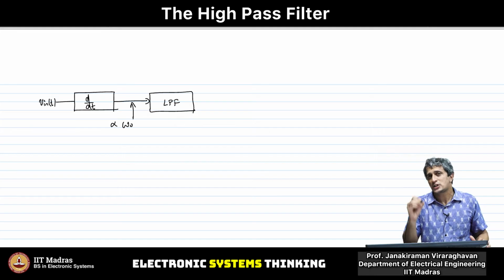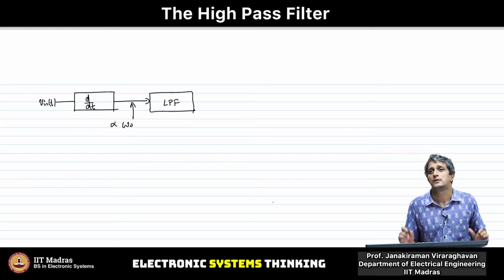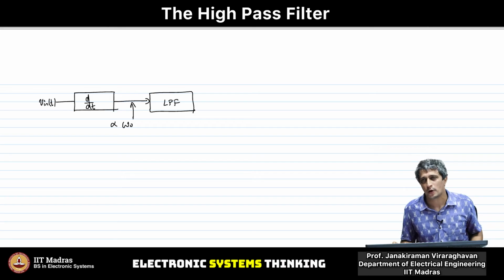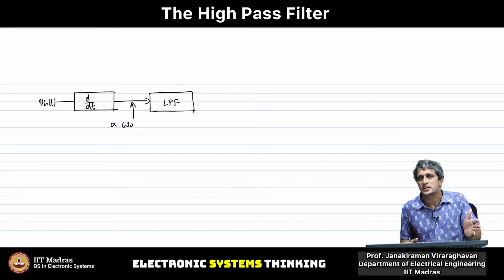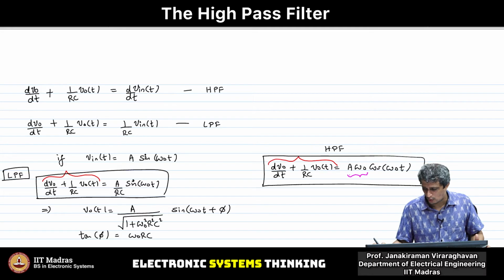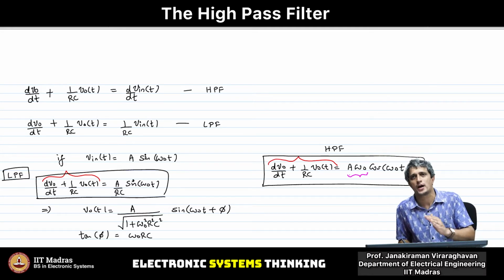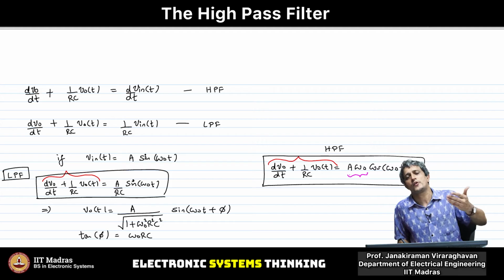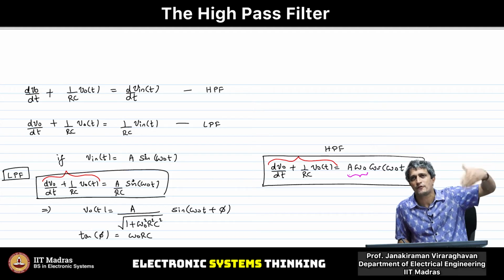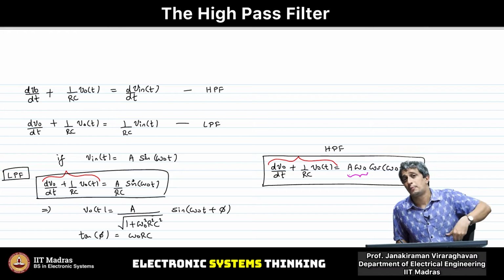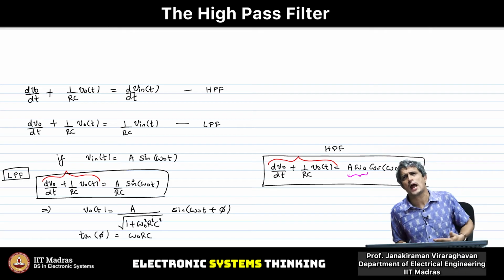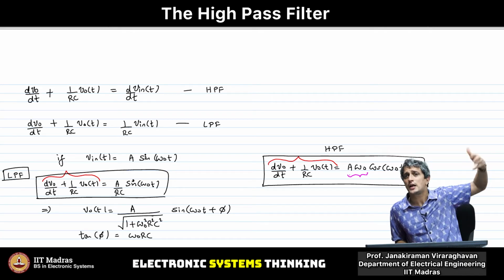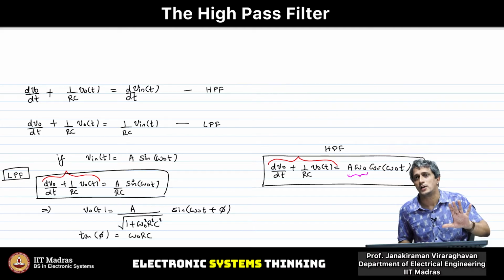So what is actually happening in a high pass filter is some low pass filtering itself, okay? And essentially what we are able to appreciate here is that, if you just look at this whole differential equation, where we have an omega naught cos omega naught t, it says that the higher the frequency, the higher the amplification factor because of omega naught. But that is telling us that if I just take the frequency to gigahertz, that means I am going to amplify it so high, that means I should get an output which is as high? Not really, right?